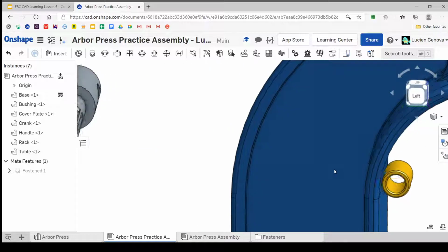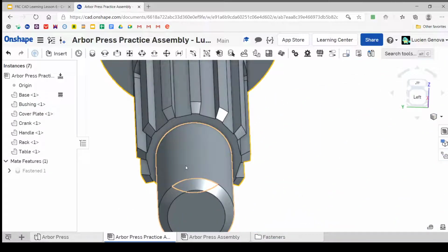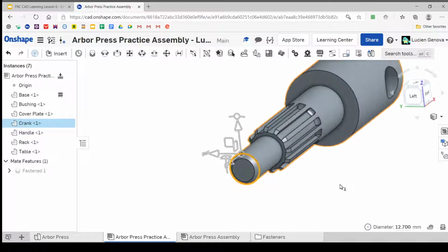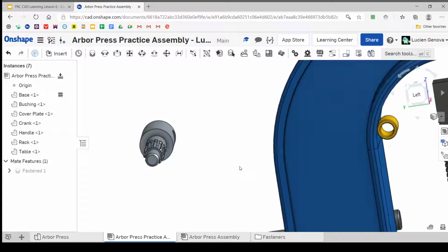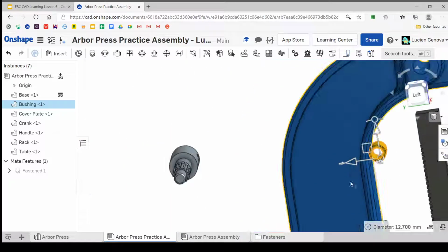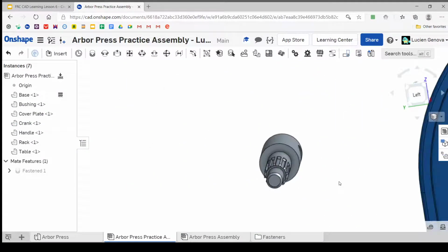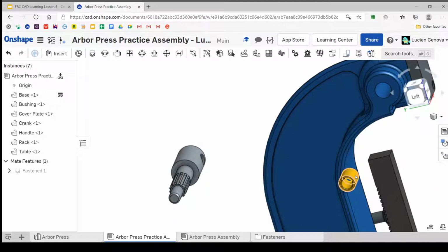And if you wanted to check the outer diameter of this bushing, it's going to say 19.05, and the outer diameter of this will likely be around 19. Oh, it's going to be 12. Oh wait, no, I picked the wrong one. That's 12, and then it's going to have to be the inner diameter here that matters, right? 12. It's again the same. There's going to be like 0.2, I believe, of clearance there, right? 0.7 and 0.7. No, they're the same. Okay, but yeah, they're going to be the same diameter, and that's always a good way to check.